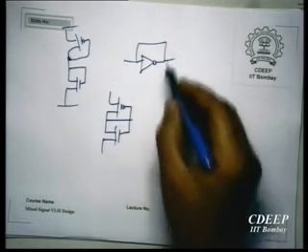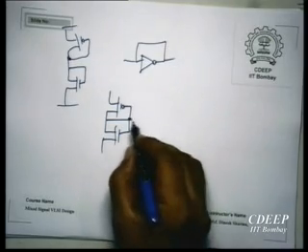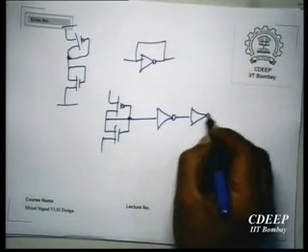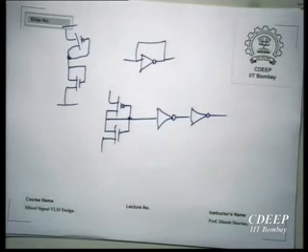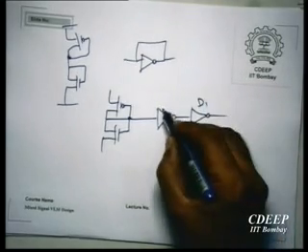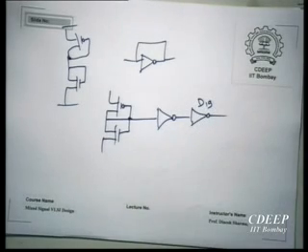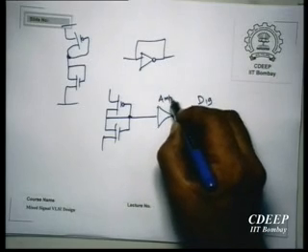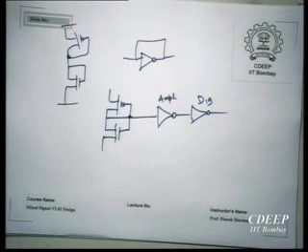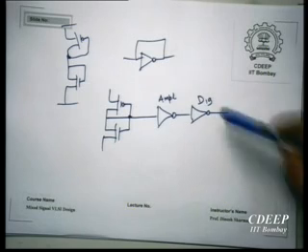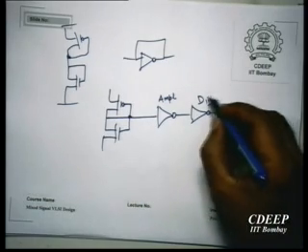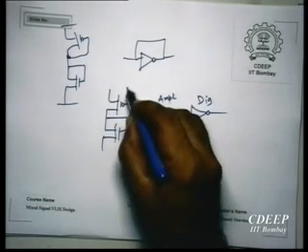So what you do is you have one shorted inverter as the load, and then you give it to one inverter which is the amplifier and another inverter which is the final digital buffer. So this is in digital mode. Even though this looks like an inverter, it is actually an amplifier, and it helps to bring the voltage swing to a healthy enough level so that the P and the N in this is completely turned off, and this is the load.